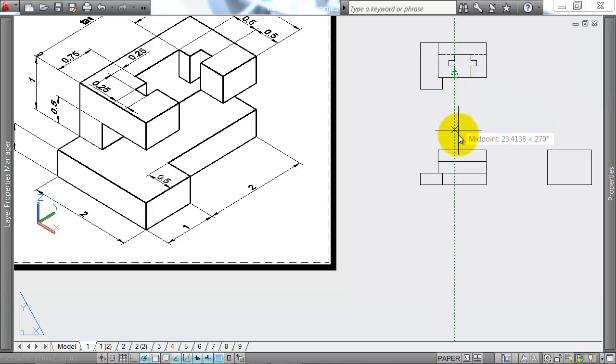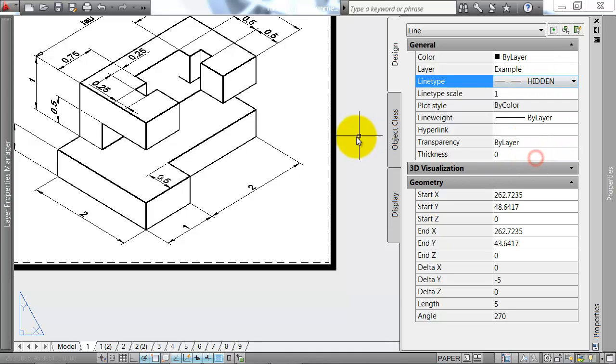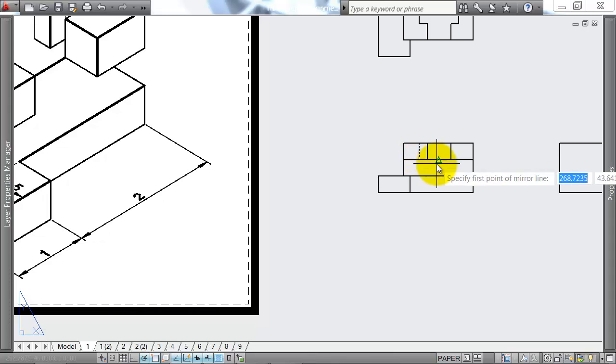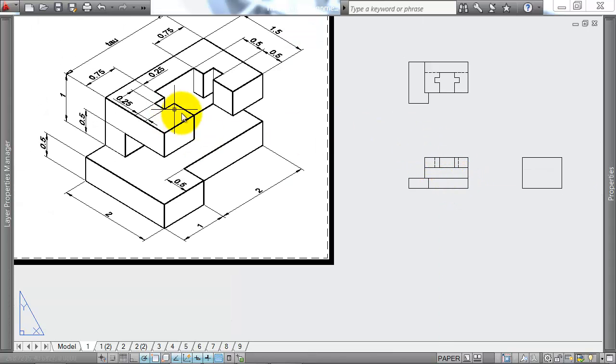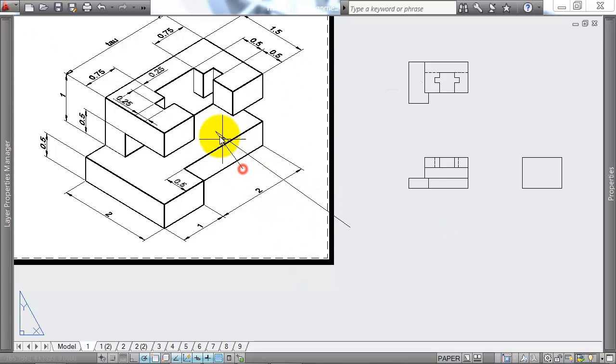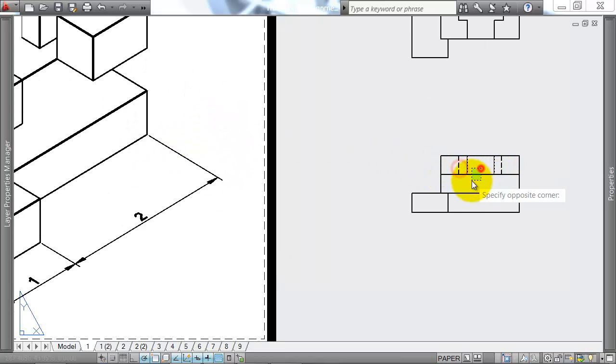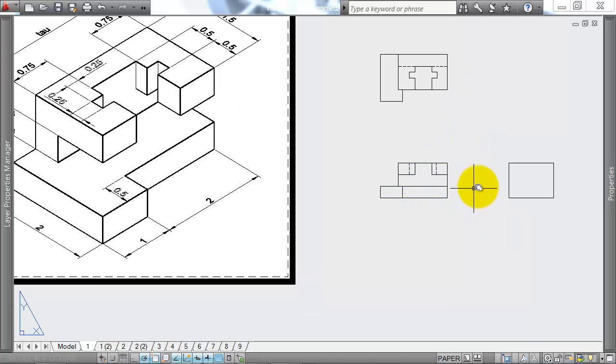What other features do I have? I can run these features down. I can run this feature down. And I can run this down as a hidden line. Make that hidden, not continuous. Keep misclicking. Hidden like so, mirrored about there. Now lastly, if I'm looking in this direction, so towards this part of the shape, I would actually not see a line here. This line in the center shouldn't be there, because this inner part of the shape is solid. It's one solid face. So I would trim off that part. Now this is one more view done.